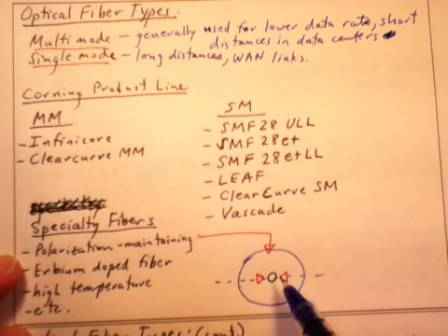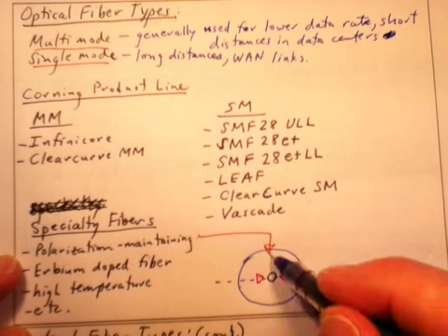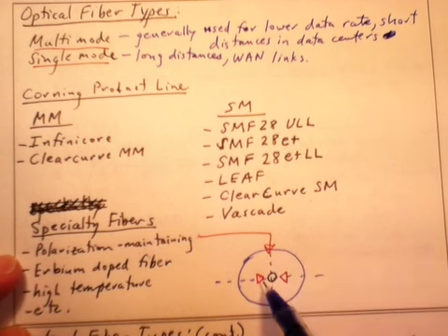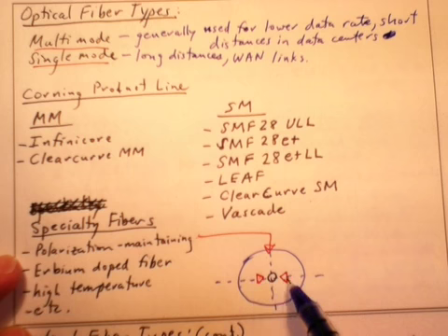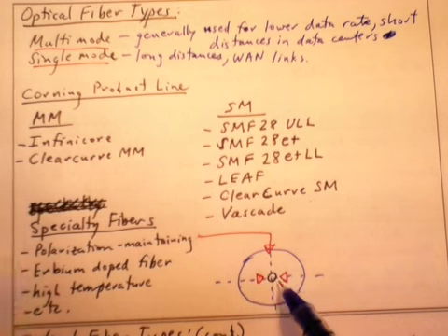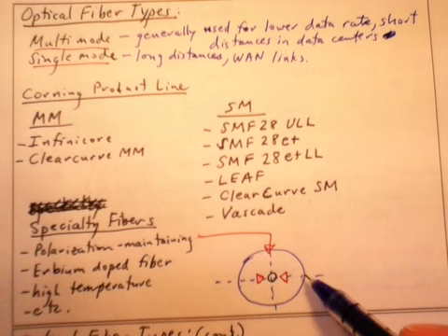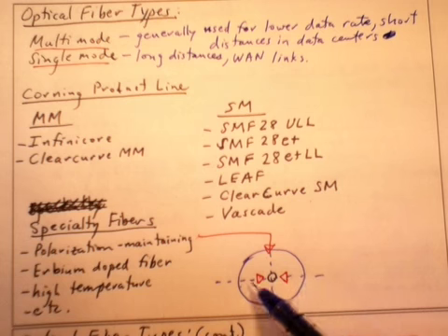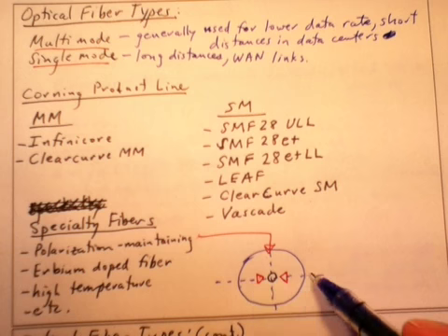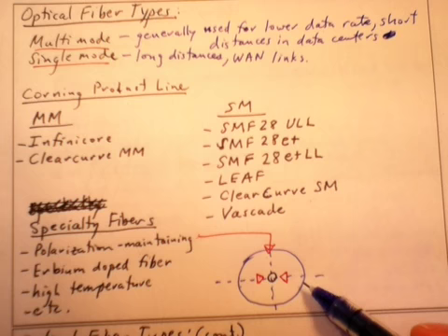If you launch light either along or perpendicular to that axis that is defined by this stress, it's called a stress member, then the light will stay polarized along that axis as it goes through that fiber. It can be very useful. They're expensive, and alignment of polarization maintaining fibers with integrated optics devices is a pretty good challenge usually.